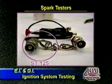Now, if you're going to do that, you have to make sure that when you inductively couple your secondary kV probe to check the calibration of your scope, you are on a negative firing event. You want the kV probe before the air gap across the spark tester in relationship to current flow. So you have to be on a negative firing event. If you are on a positive firing event, your kV probe is downstream of the air gap, and your kV probe picks up the voltage potential after the voltage drop across the air gap of that spark tester.